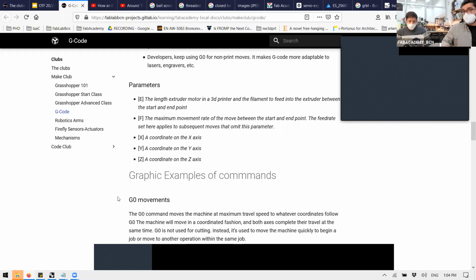Or for example, you don't see it here, but the machine says that before using it, you need to warm the spindle for 3-5 minutes. It's a good workflow. You can introduce that in all your files, and basically it's 3 lines of code.